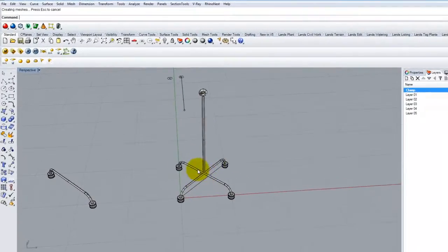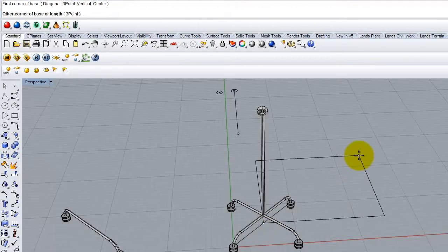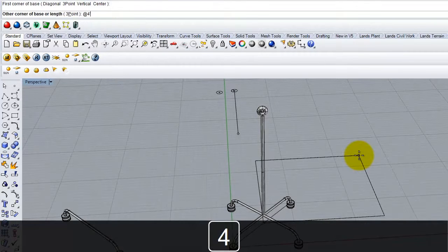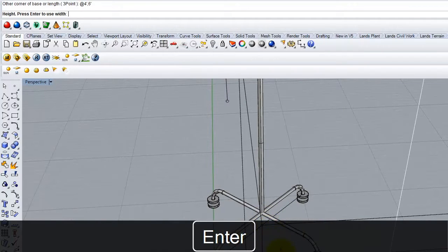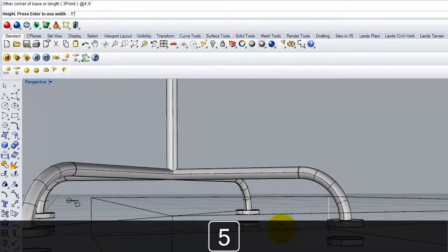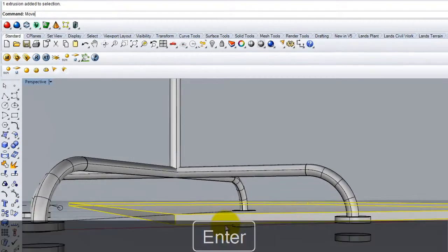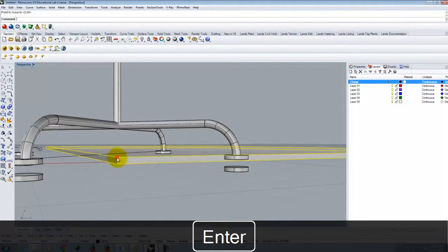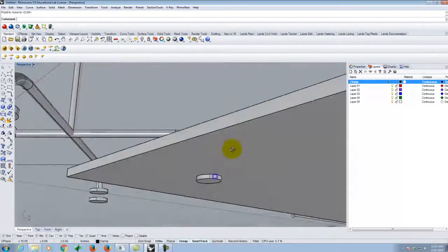So I'm going to go from here, and I'm going to create the piece of glass that is a 4x6 pane, which is just simply a rectangular box. And we'll start, because I drew this curve, I can start right here in the center, and I'll say at 4 feet, 6 feet, and the thickness is going to be ½ inch, so it will be -0.5 inches. There it is. It has to go down a 1/4 inch. So let me just go ahead and move this by a 1/4 inch, and it now goes between, right, this and this.